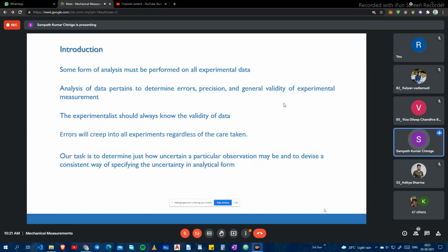The other test to find out the frictional force is the motoring test, where we rotate the shaft. We are not burning the fuel or anything. We are just rotating the shaft by means of an electric motor. By rotating the motor, you are actually moving the engine and trying to find out the frictional power. But here, there is no combustion taking place within the cylinder, no temperature, and therefore no expansion of the metal, and therefore the frictional forces are supposed to be lesser.